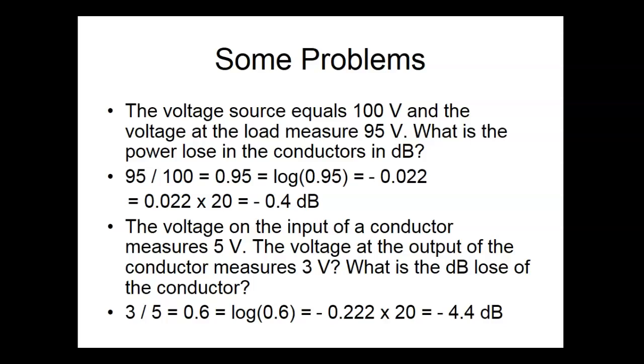I learned that trick when I said to my friend about my clamp-on ammeter, I'd like a more accurate measure. He said, well, just loop the wire, Rich, and I'll loop. I said, man, that was so cool. And then it makes sense, because it's basically a transformer. I had put it around the wires, and it wasn't measuring all that. That's too low. Well, the problem is you're measuring the current in the neutral, which is always flowing opposite of the current in the hot. So this is going this way, this is going this way, and it's always canceling it out. So if you're going to use a clamp-on ammeter, you only want to put 1 wire through it.